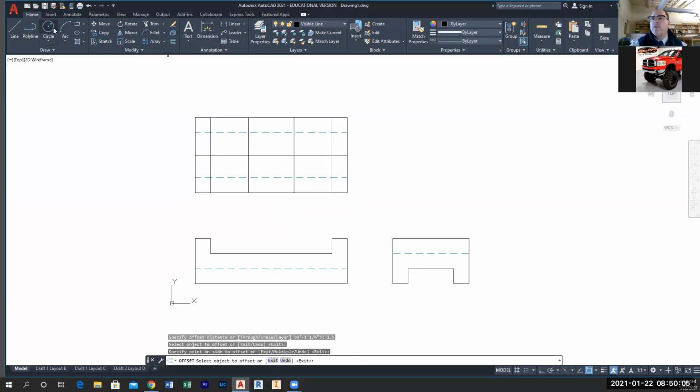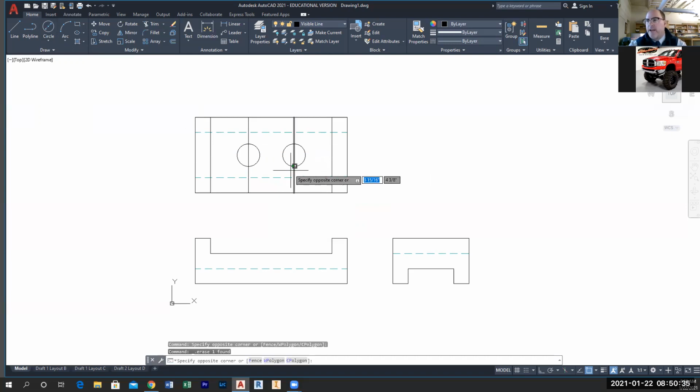Now I'm going to do circles, a circle from here, and the circle says 3/4 drill, 2 holes. So this is going to be 3/4 drill. Let me do this again because I'm on a diameter. I want a diameter. So then I go here and then I go 0.75, enter. I can go ahead and copy that selection from here to here. Boom. Okay. And then these are just center lines to find the location, but I'm going to go ahead and put center lines in there later.